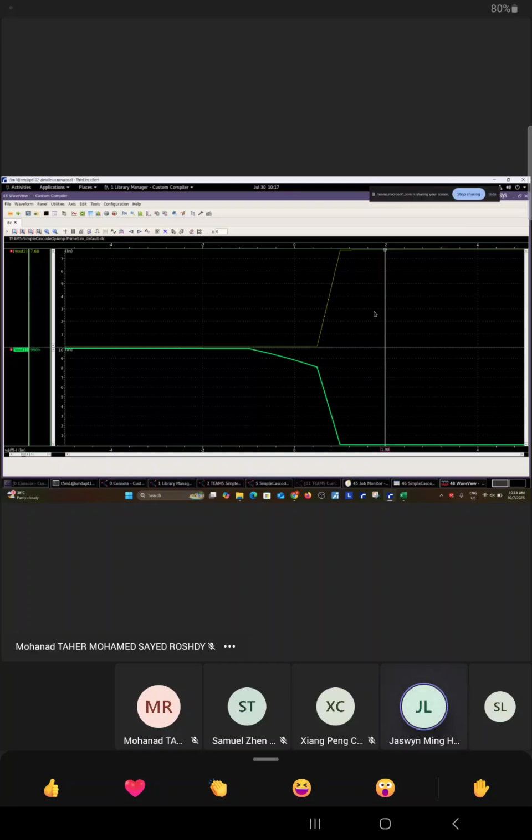But then let me see an open loop. What you can do is like this. You put V in minus to be VDD over 2. Then you put V in plus to be a sine wave that swings around VDD over 2. Then you can see, depending on the amplitude of your sine wave, whether it gets clipped out or not. Later on, we do a simple experiment, don't worry.